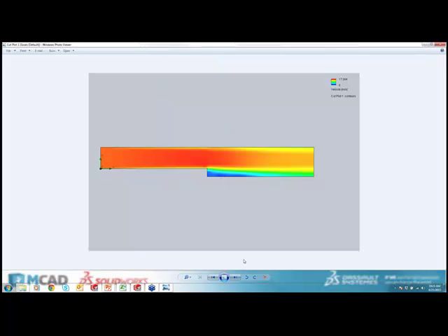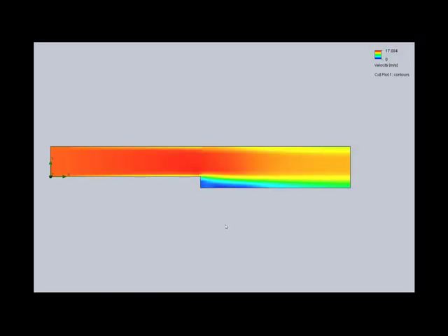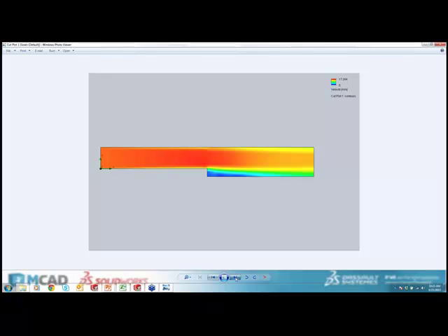So you'll see here, this is cut plot 1. This was with goals. If you compare that with initial conditions, wow, didn't mean to click that. If you can spot the difference, it's just barely apparent down here, but there's almost nothing. This is the more refinements. You can tell that there's a big swirl that developed a little bit more, but nothing else really changed. This is the no goals, back to the original. This is with CPU time, nothing except that. And then this was just the simple refinement one.